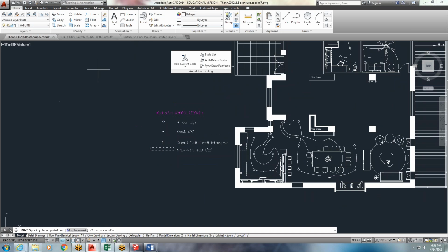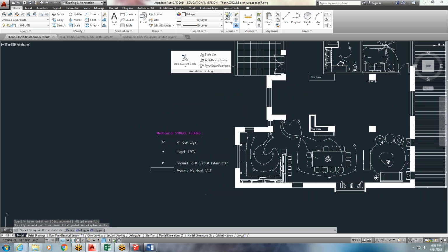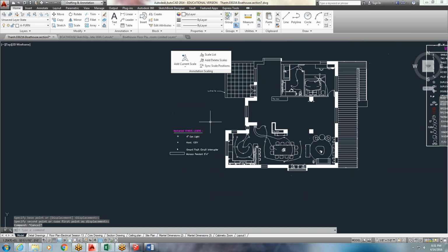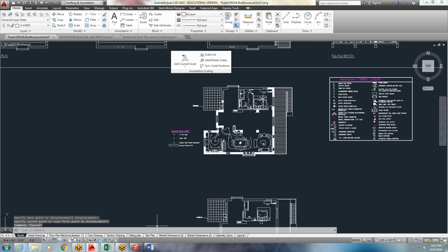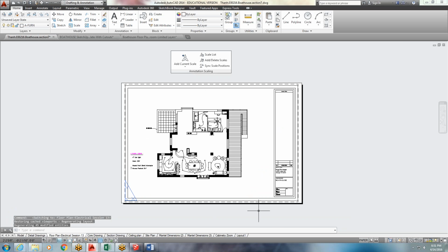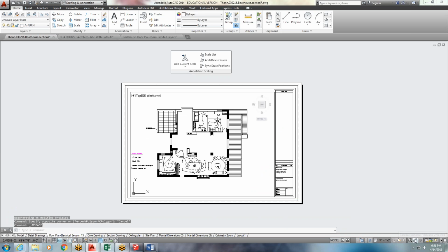So let's see. Put it where you want it. It could be to the left, it could be to the right. Kind of align it with some point on your drawing. So I like to align my text just so there's a clear visual edge that it's following. All right, then I'm going to go to my new floor plan electrical session 13. And now at this point, I might want to unlock my drawing when I'm in it. Unlock. Notice there's two different locks. Some of you do this, and that's not correct. You want the yellow one.